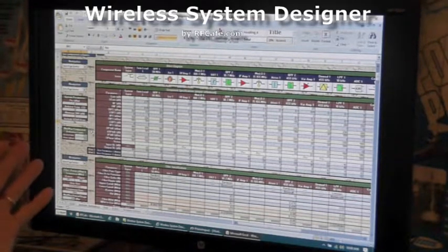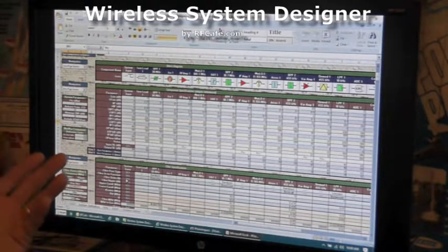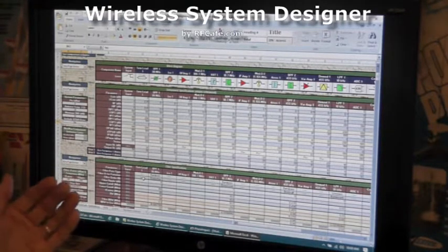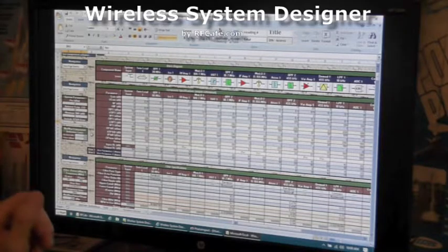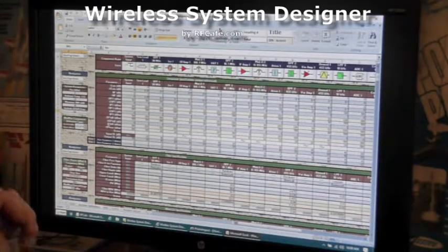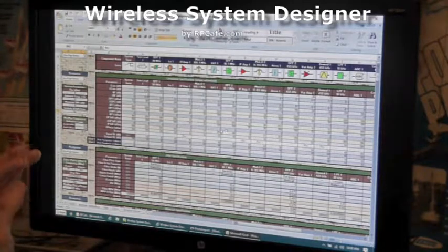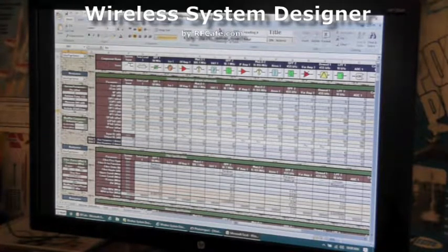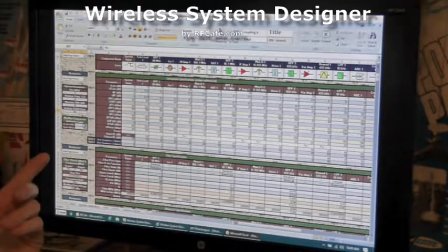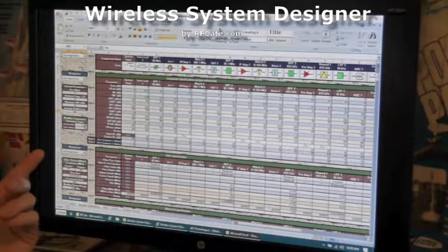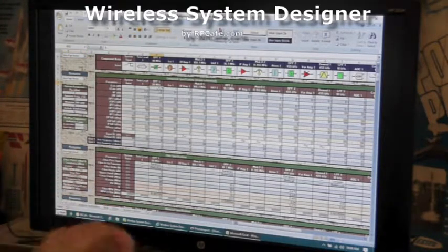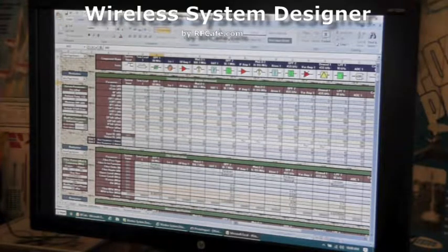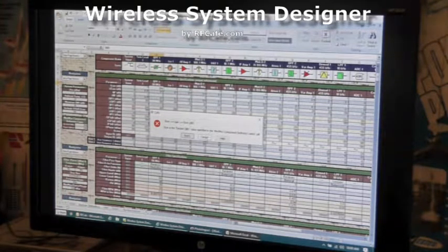When you have the VSWR included in the gain, the cascaded gain calculations, it also affects all of the calculations that use gain, which are just about all of them. So keep that in mind. I have over here, because all of these input cells are error checked or error trapped in one way or the other, a place for the minimum and maximum decibel and power numbers that you can put in here. Right now they're set at 250, so if I try to put a value of 300 in here, it just says that it's higher than what I set for the limit.